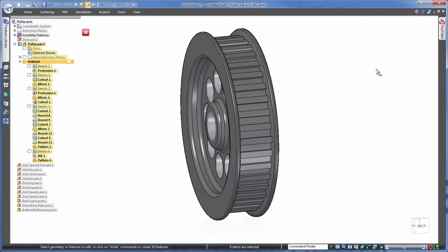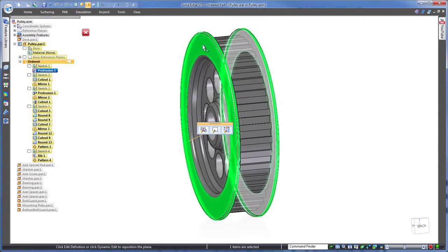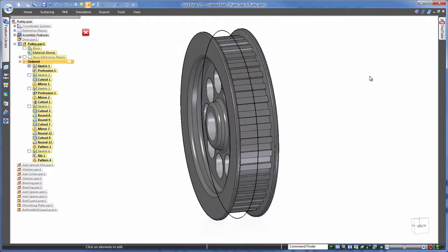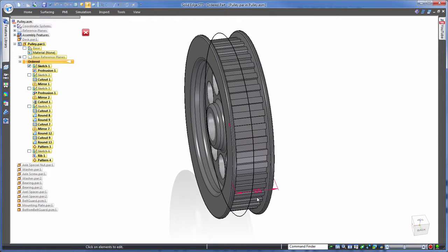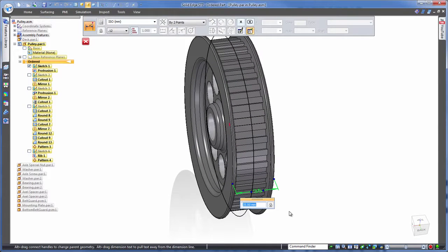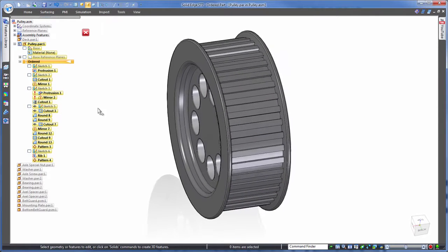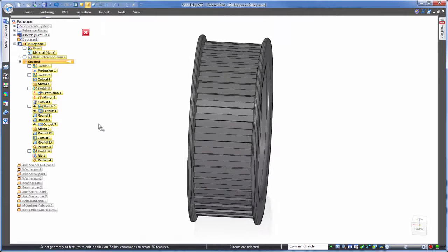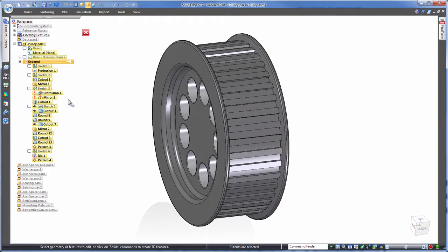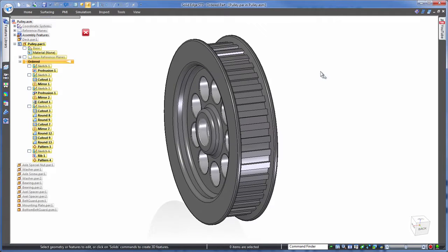It can be tricky finding which feature is the one that we want to edit, however Solid Edge does assist us by picking up the relevant feature after we click on the model in the graphics area. So let's take this 35mm dimension and change that to 55mm. Simple. Oh, no, wait. Because this is history-based editing, there are dependent features further down the tree on the left that this has caused issues with, damaging our model.